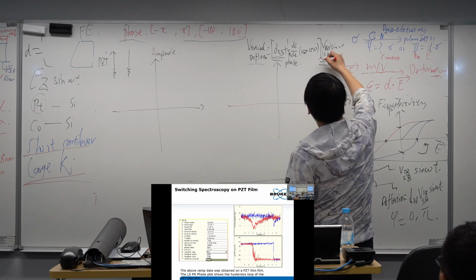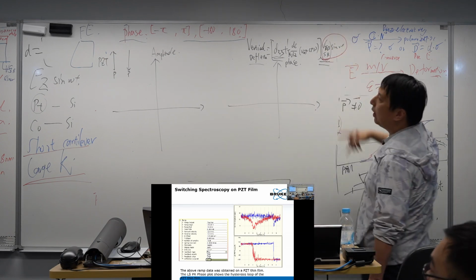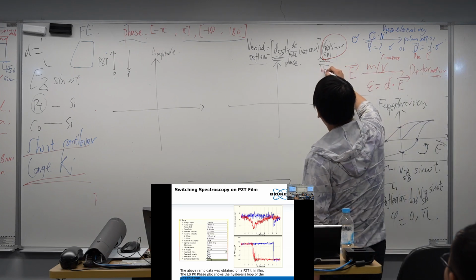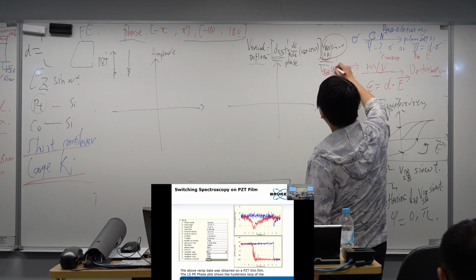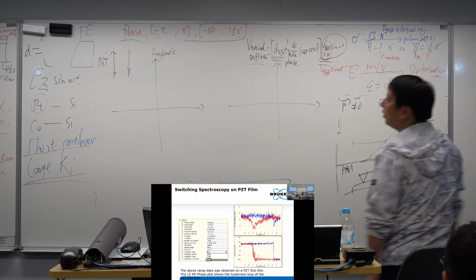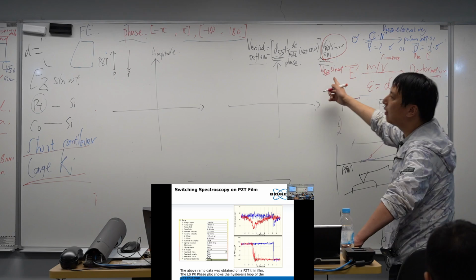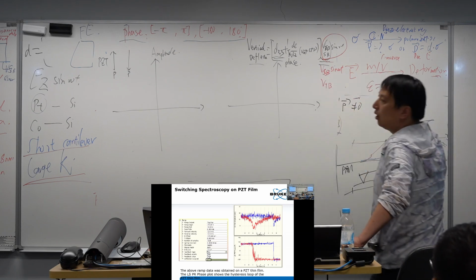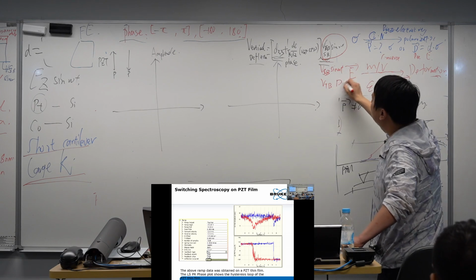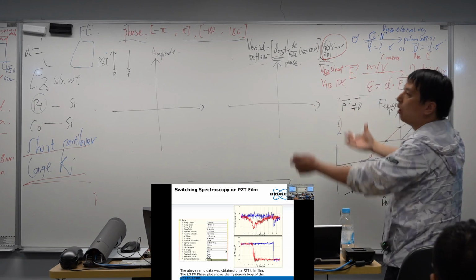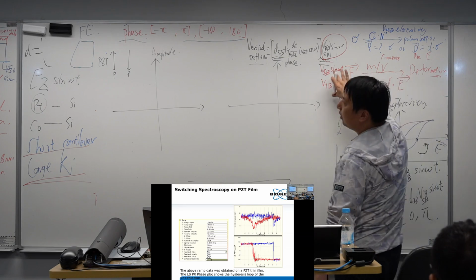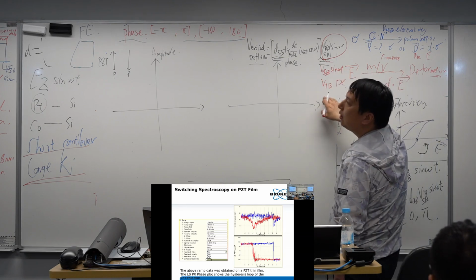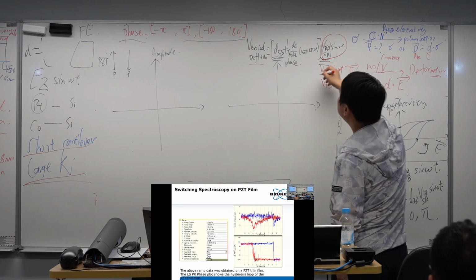Since this one is already occupied, for example, if I apply the AC voltage on the sample bias, I can apply the tip bias to be a DC voltage, or I can do it the opposite way: apply the AC voltage on the tip and adjust the DC voltage on the sample.